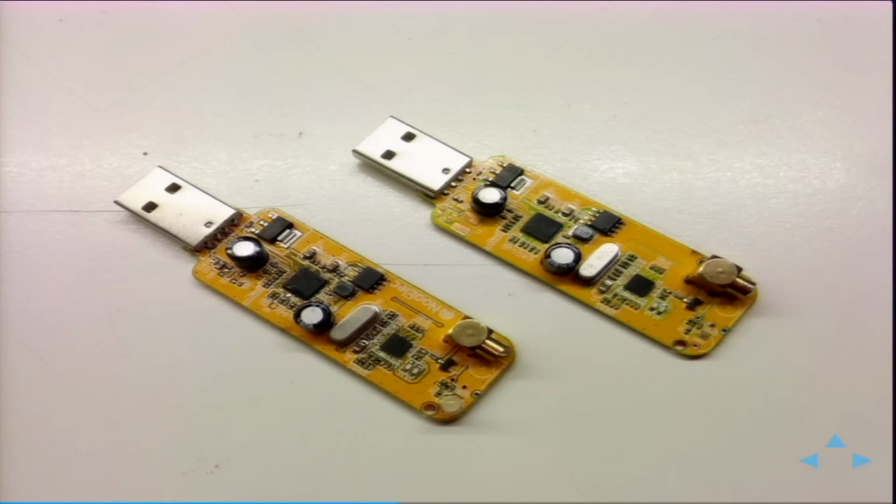For the receiving part, we are using everyone's favorite DVB-T. The off-the-shelf solution caused some instabilities, so specifically we had some problems with the PPM errors, so we decided to go with the modded ones that you can find in the market, with the patched oscillator, so you can have a more stable product.